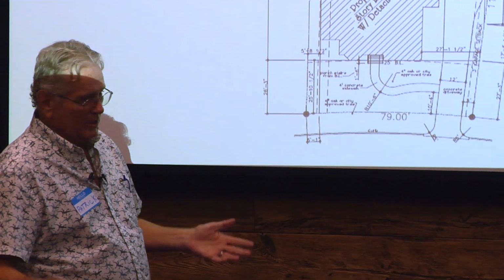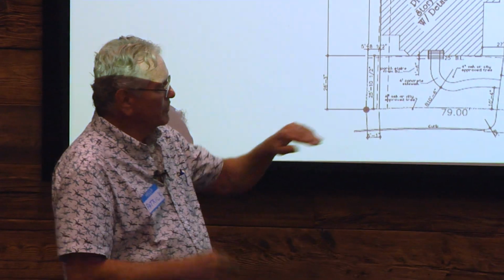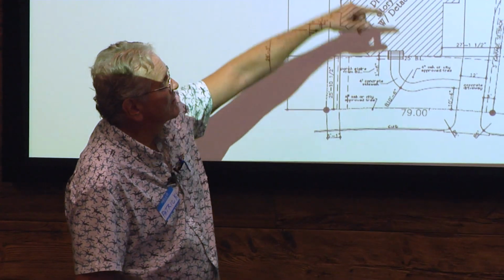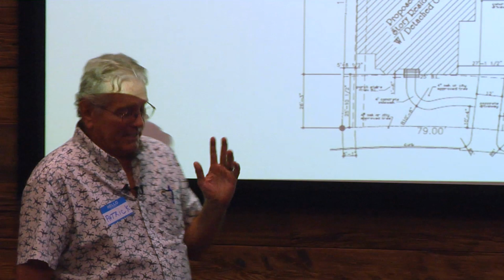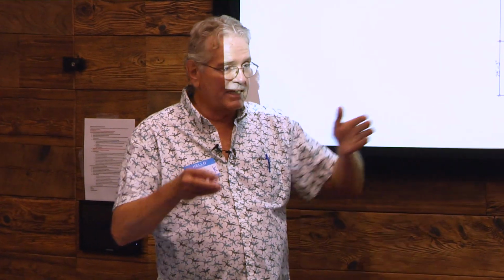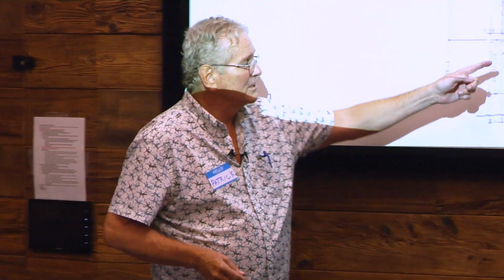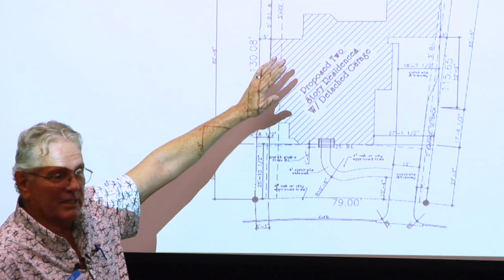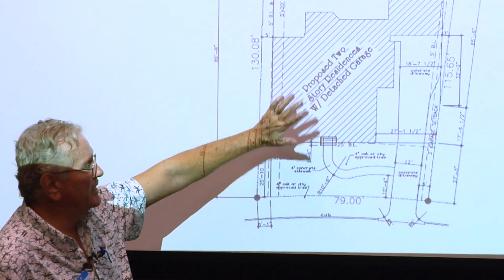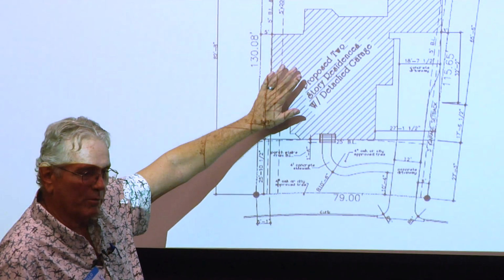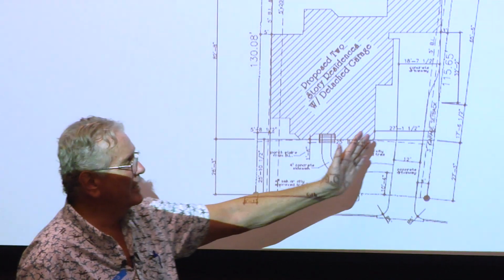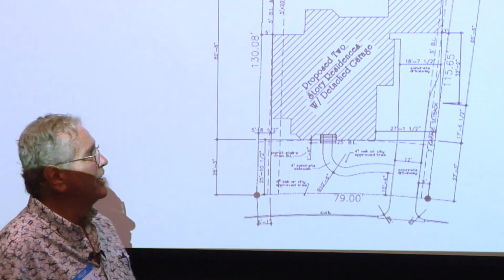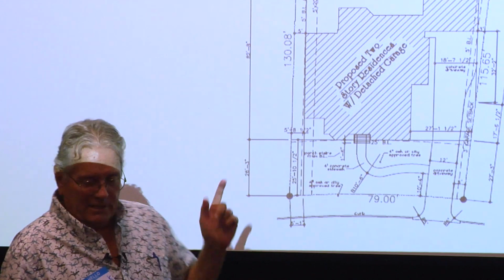Now, as a builder, I really like a little bit of wiggle room. They didn't put much wiggle room there at all. I mean, they crammed it in there. And that's a whole different subject about getting a form survey done, especially on a house like this. When the foundation guys come in and lay down the perimeter of the house, just this line right here, have the survey company come in the day after and don't do any other work until you get that all figured out. They do this form survey and send it back, and everything is sitting in the lines as it needs to sit.